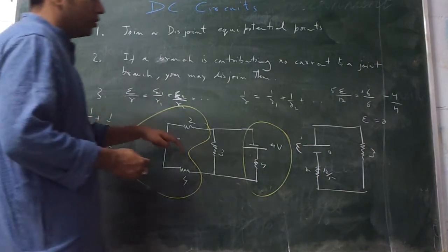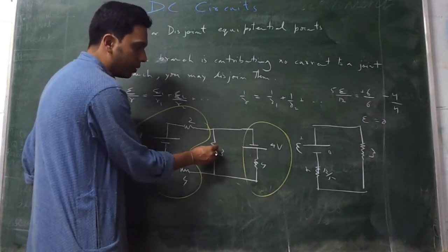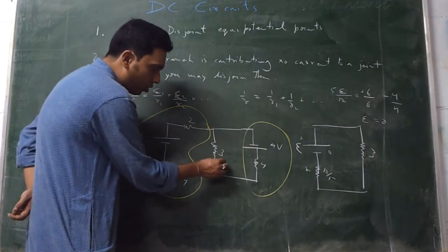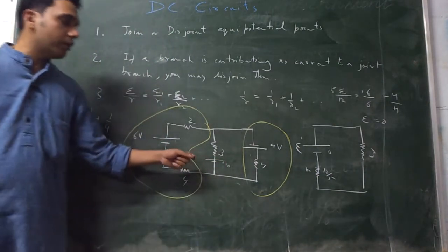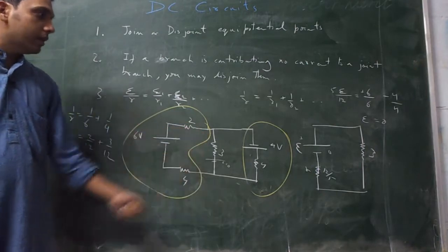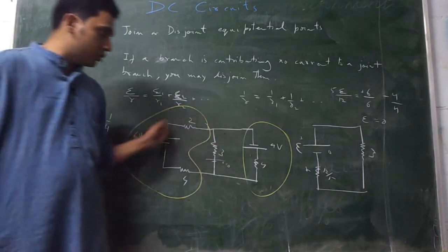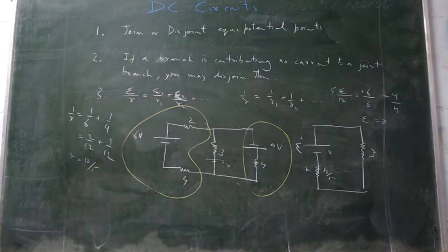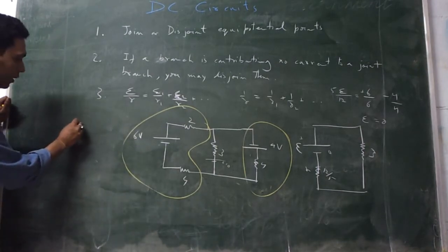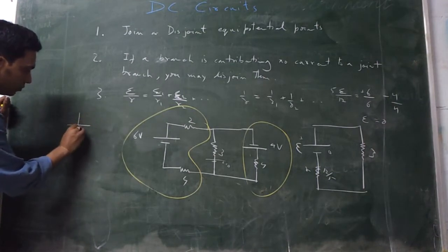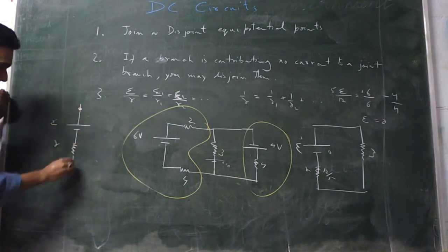We could have also done this using these three batteries, this and this, I am calling this a battery with the internal resistance 3, a battery of EMF 0. If there was a battery of suppose EMF 0.001, you could have applied the formula or not. So all three are parallel, and we can again use the formula, and the whole thing becomes a single battery and a single resistance of value E and R, wherein the circuit is open now.